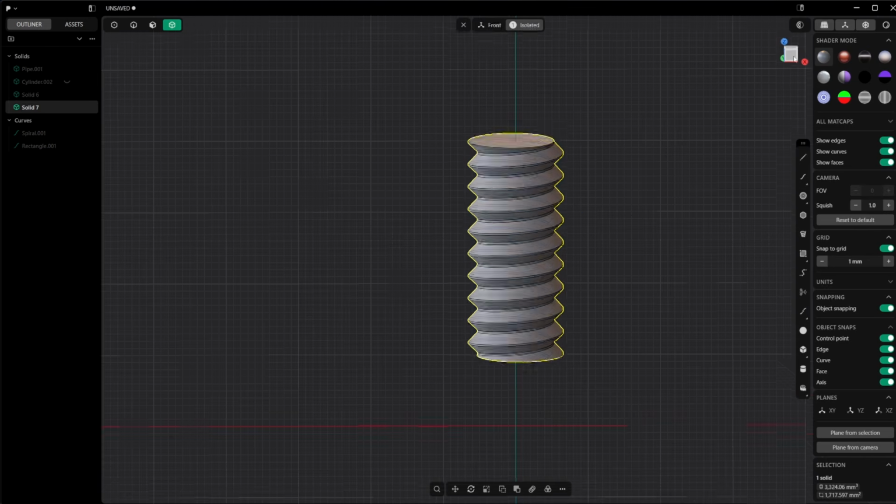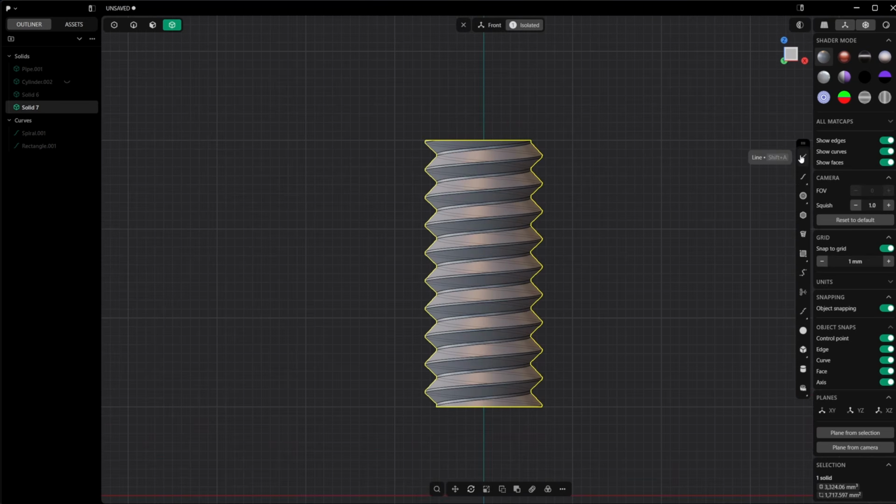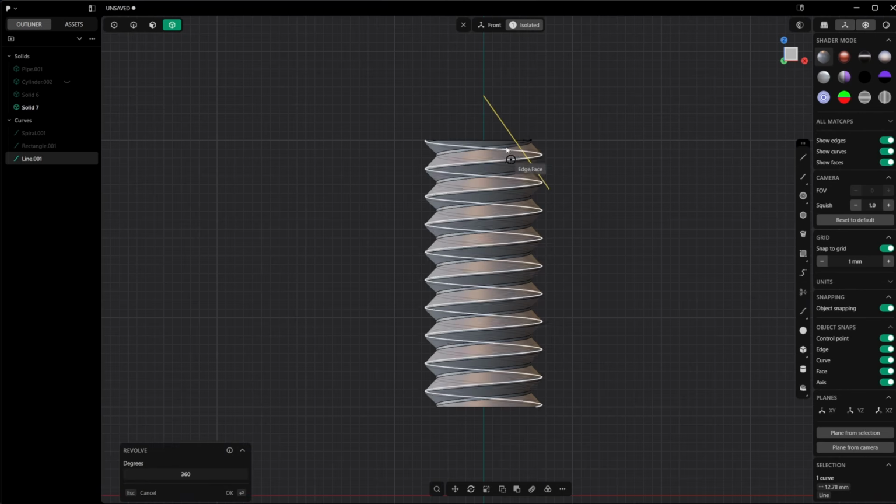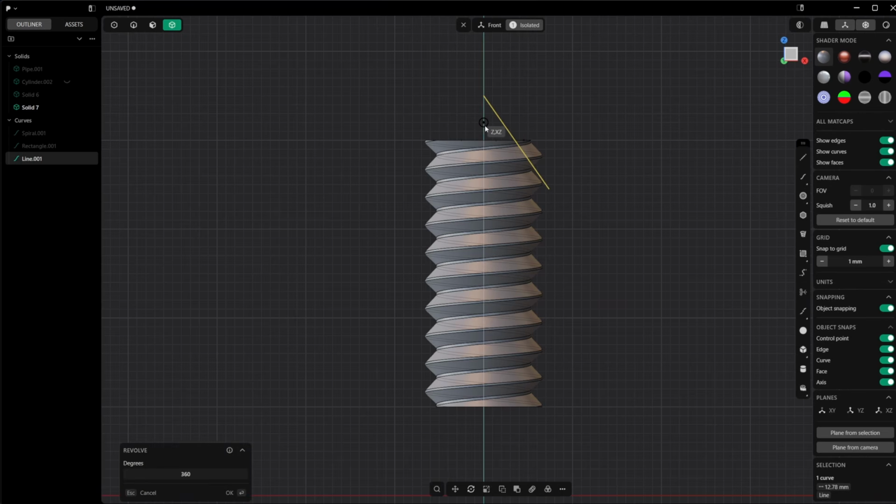It's going to be a little difficult to insert this, so I'm going to take the line tool and give it a point. I'm going to create basically a hat here. I'm going to give it this kind of angle, something like 50 degrees, or let's make it clean. Let's make it 55 maybe. It doesn't really matter. Press F to bring up the menu, REV to revolve, click revolve. Select the y-axis in this case, and push it up.